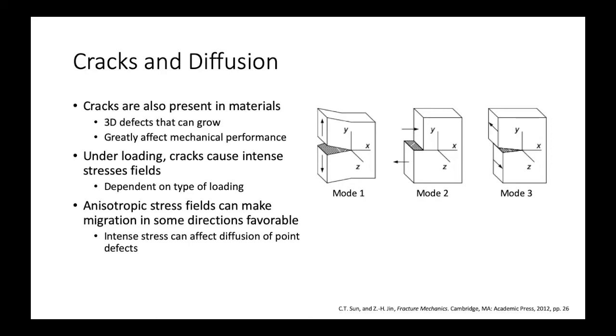The nature of the stress field around the crack is dependent on the loading mode of the crack. The simplest case, where the crack is being opened, is called Mode 1 loading. Mode 2 involves pushing on the crack face, and Mode 3 involves tearing the crack.